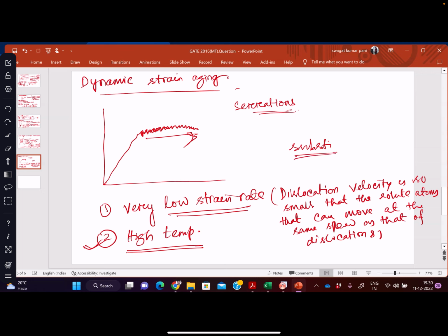But for interstitial atoms, like we have atoms here. This is an interstitial atom, so it can move here, here, here, any direction easily. And suppose we take a substitutional atom that we want to diffuse. So we need at least a vacancy.